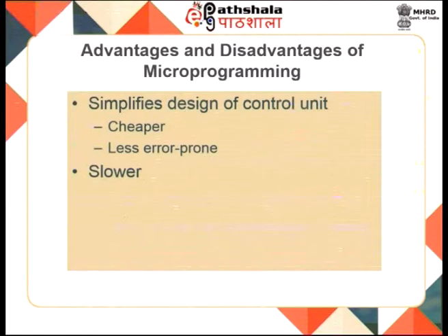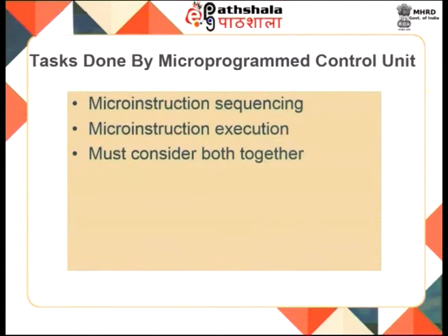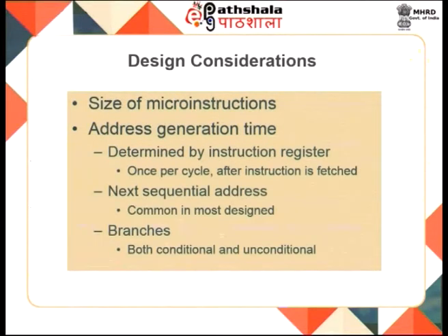It is cheaper and less error prone, but it is obviously slower compared to hardwired control. The tasks done by the microprogram control are basically micro instruction sequencing and execution, and obviously you will have to consider both together to get an optimized design.